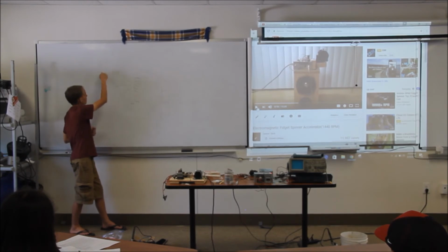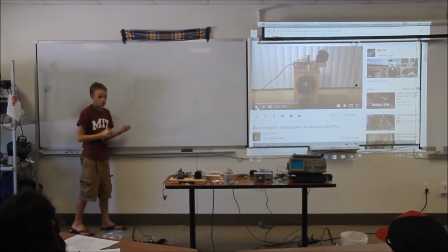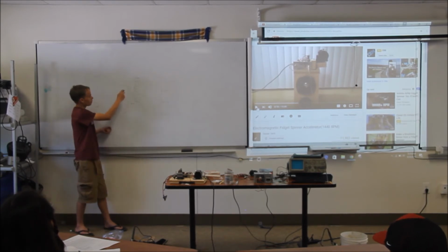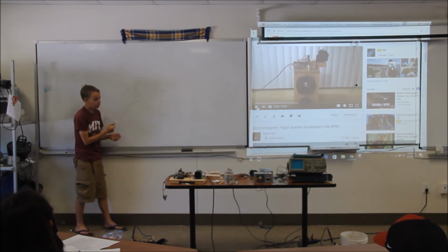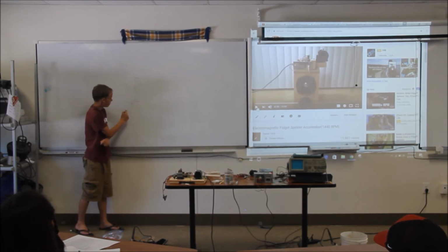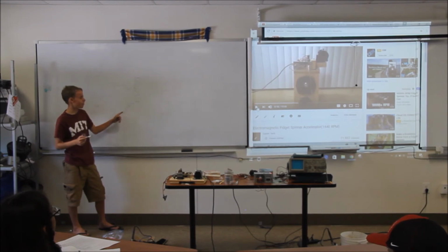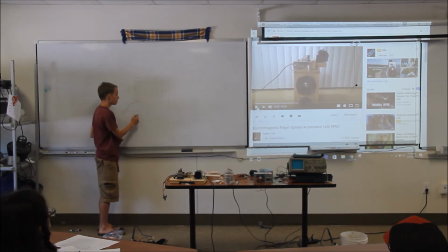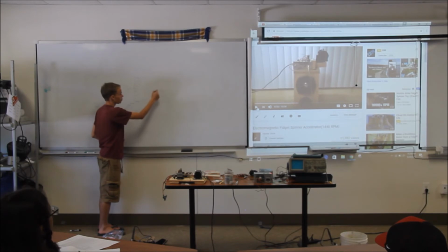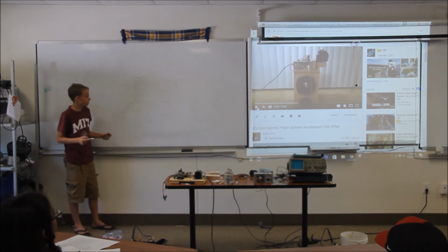And pretty much what happens is, whenever this spinner comes near this magnet, then there will be this other switch right here, which is called a magnetic reed switch. So when this magnet passes this reed switch, then it will turn it on. It has these two little things inside right here, and these two little things click a little tiny switch. Now, the switch can't really turn on too much current, so it needs to go through this MOSFET transistor.